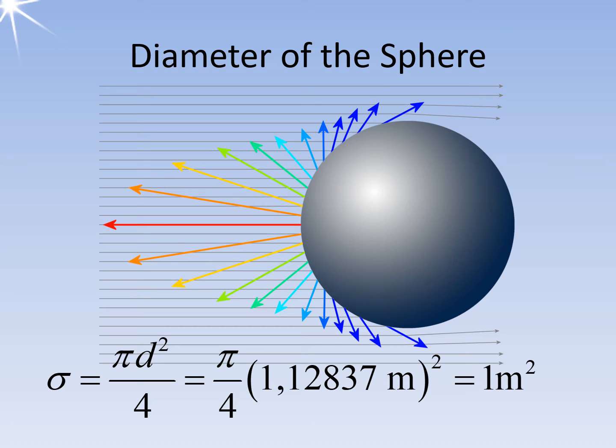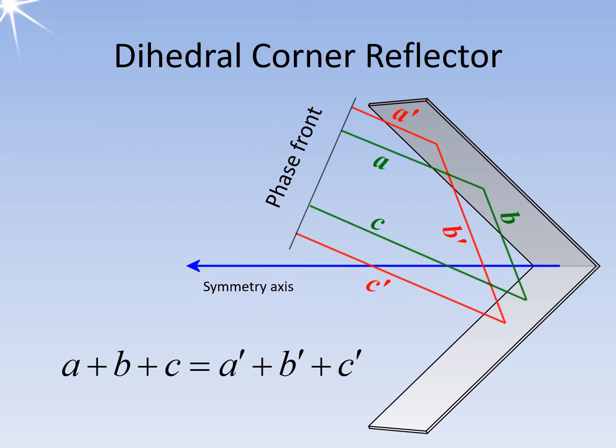Unlike the isotropic antenna used in antenna calculations, an isotropic reference reflector can be constructed in reality. However, it would be bulky due to its size. In a measurement setup, a calibrated corner reflector can also be used because the radar's direction and its transmitter's frequency are approximately known. A corner reflector consists of 2 or 3 electrically conductive areas that are positioned at an angle of 90 degrees to each other.